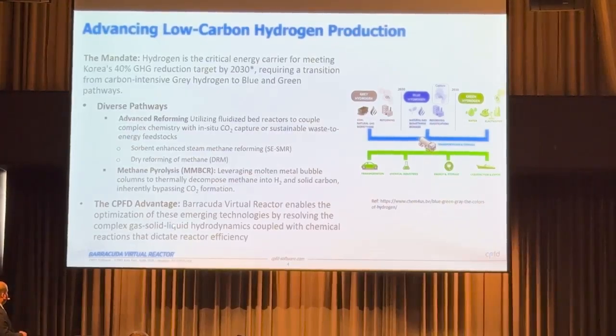And Barracuda is actually very well positioned to be able to model these applications, as we'll see. The key in these, as you dig deep into them, the problems are quite complex. You basically have not only a complex multi-phase flow, just from the core flow point of view, but then you also have to couple them with reactions, essentially. And these reactions can happen on the particles of the discrete phase. These reactions can happen in the gas phase. And all of this is actually happening simultaneously at every time step. So you not only want to have these solvers which are able to simulate large-scale domains, right, like real-world domains, but being able to solve them stably as well. That's where the power of MP-PIC and Barracuda really shines out.